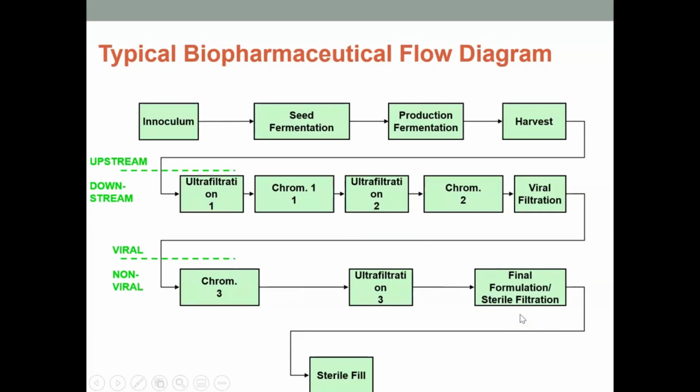So to show you that in a little bit more detail, in biopharmaceuticals, you often hear people talking about upstream and downstream. Upstream is the process where it's defined from the early cell isolation and cultivation to the part where you will harvest your cells. And it's the part really where your microbes or your cells are grown. Step 2 then of the upstream is the purification. So you want to get your desired density of microbes before you would harvest them. And that's done with ultrafiltration and chromatography.